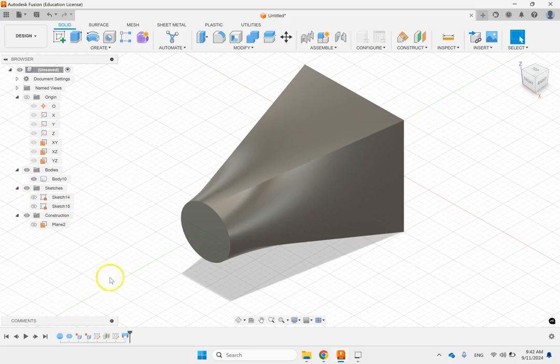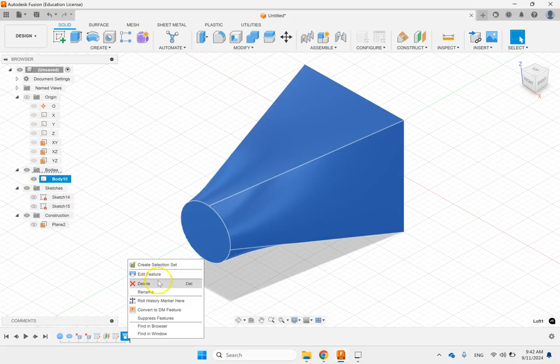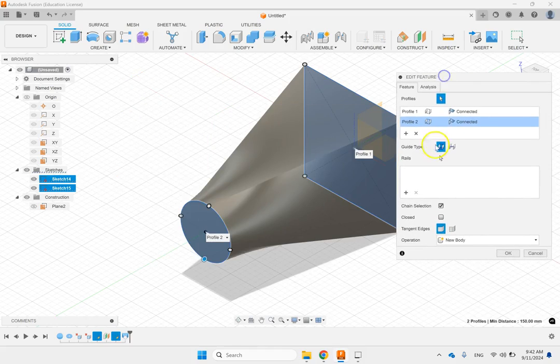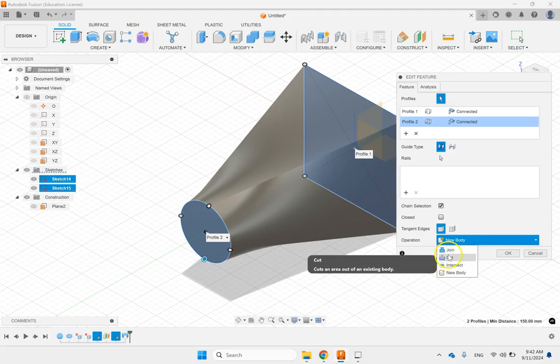Now you don't need to make it this simple. If you want, on the sides, instead of connecting these key points with lines, you can connect them with rails or guides. And the guide could be either a center guide, or it could be on the top and on the bottom, on the left and on the right. Okay, so you can do different things. And again, you can do loft or cut loft, right? So there are lots of things you can do.